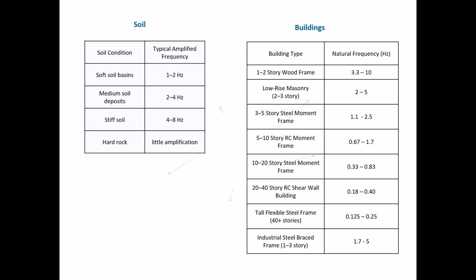By the way, what we're most interested in with buildings are the lateral natural frequencies, because buildings tend to be flexible in the lateral axes. Buildings tend to be very stiff and strong in the vertical axis, because the building structure has to support the weight of the building and all of the contents. We're not so much worried about vertical response behavior, but we are concerned about what's going on laterally with these buildings. More about that as we go along.